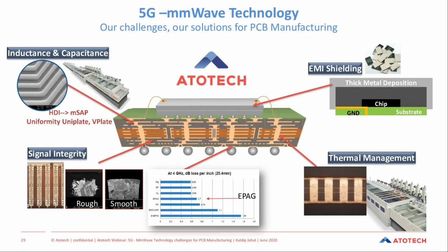And what I'm pointing to on this slide is that if I break down some of these main categories, Aditech has been working in impedance control by moving to finer lines and spaces in terms of the methodologies of plating and the additives used and the uniformity.